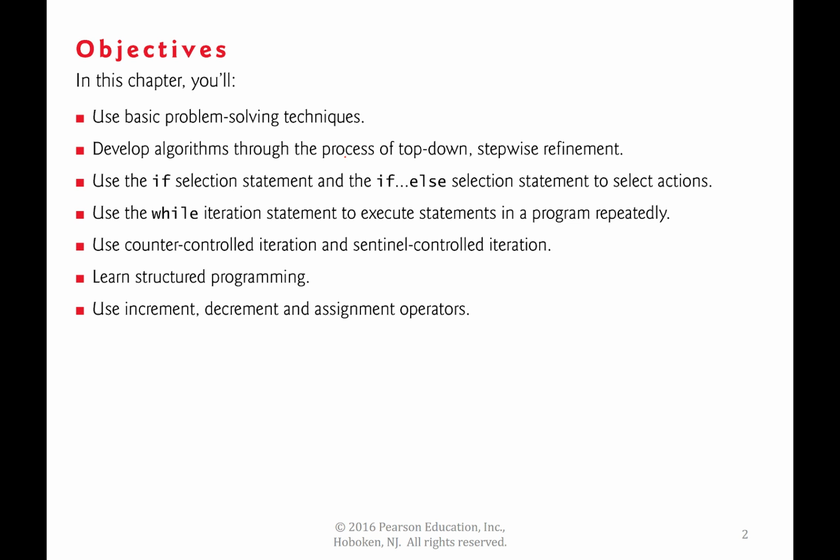I spent 3 months on the project full time. I was brought in as a consultant to figure out why this test kept failing, because from a theoretical standpoint, it should work beautifully. As it turns out, the failure was caused by a difference in thermal mass between the unit under test and the reference unit, which we knew did not leak.